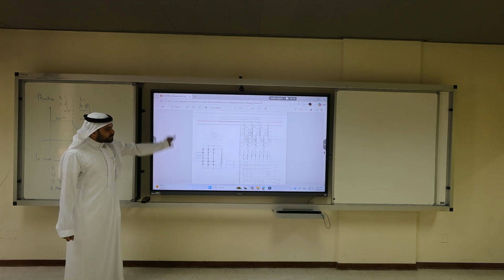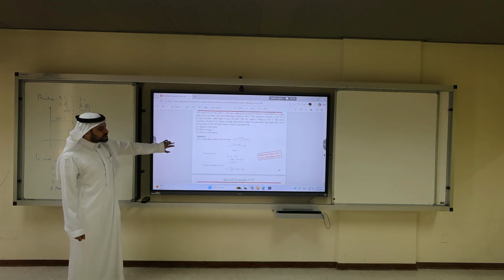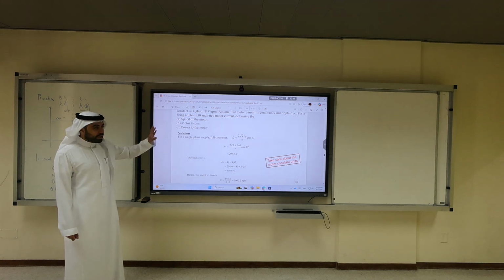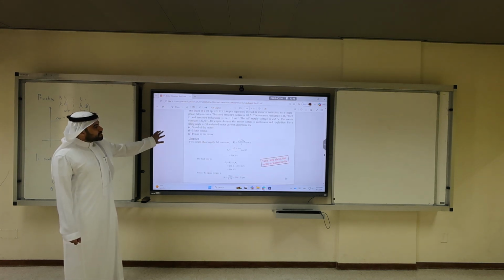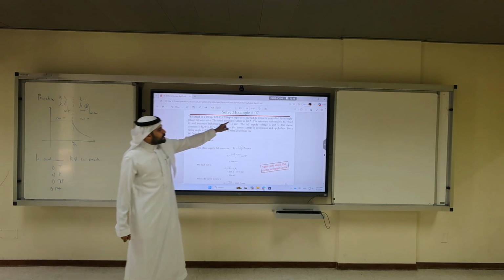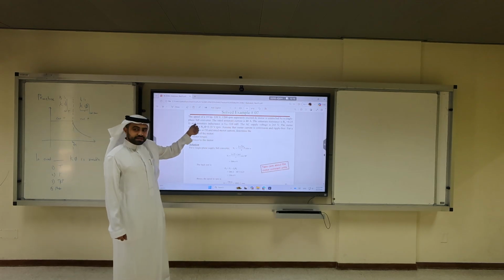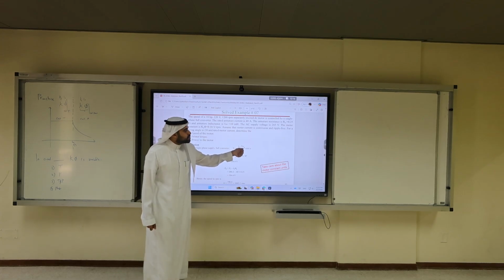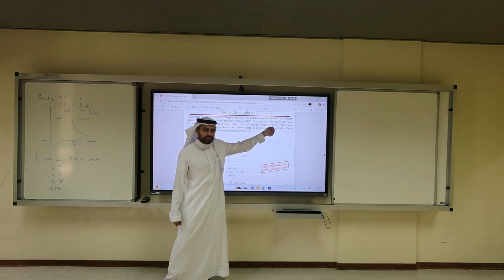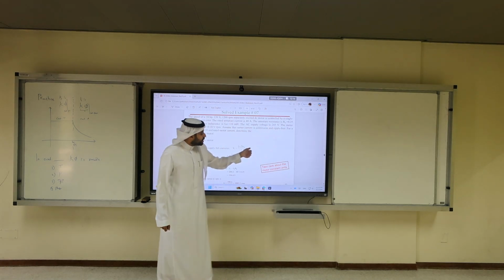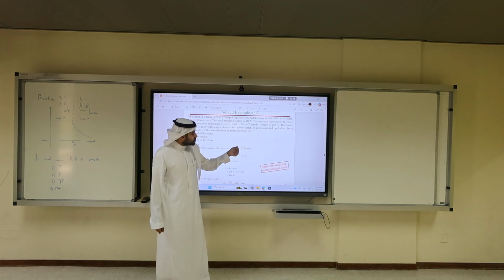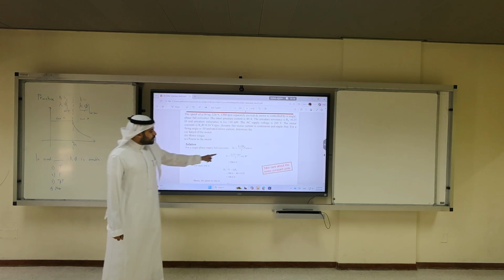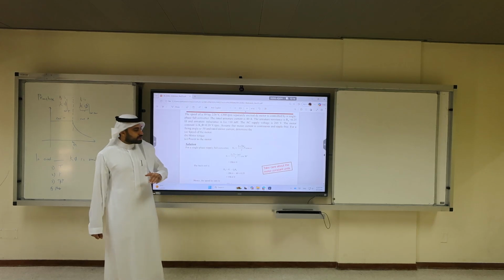What's next is the examples that we solve. The first example, I think we tried to solve it, but I'm going to show you the example. We are really late. This example is separately excited, controlled by single phase. This is single phase, so VT would be V phase, which is 265. This is single phase RMS, it's not line to line, times cosine alpha times this constant, 2 square root of 2 over pi. Now, at 30 degrees, you calculate VT to be 206.